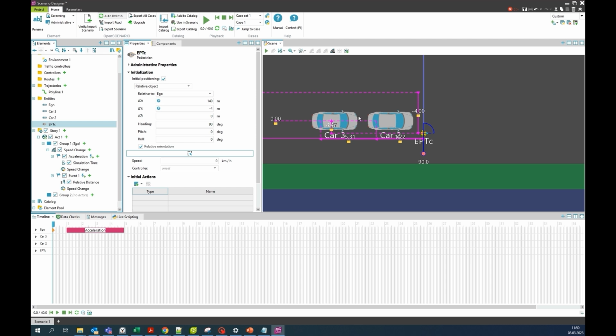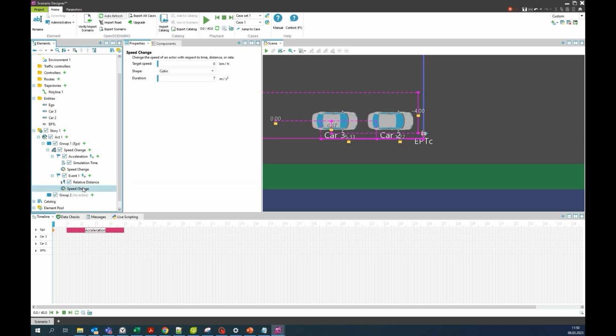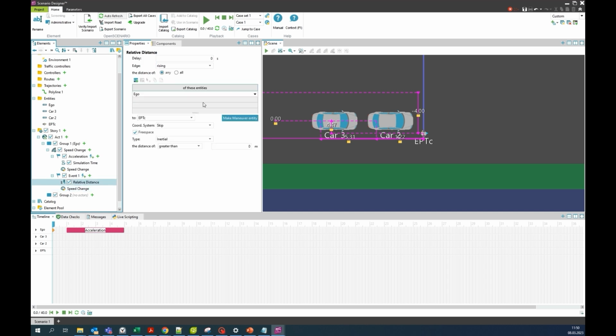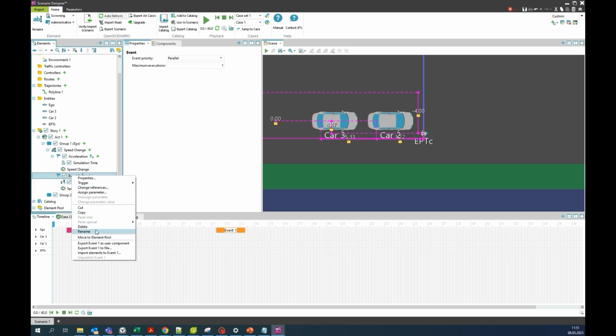So in this case, it would be, for example, for this vehicle, from the front of the vehicle to the left arm of the pedestrian. Okay, and longitudinal distance is what we want when it becomes less or equal than, for example, 20 meters. So the braking event is defined.